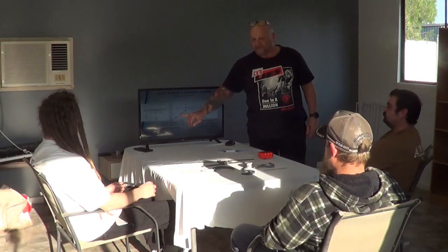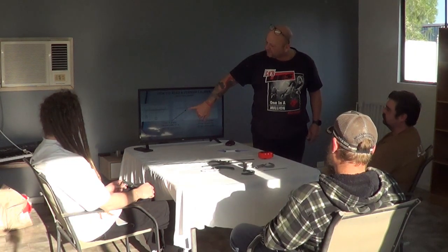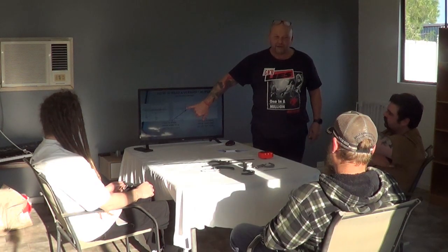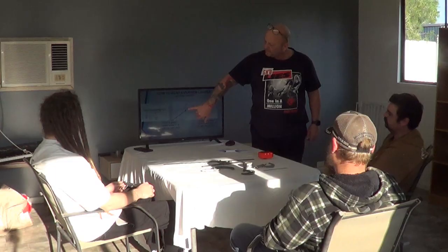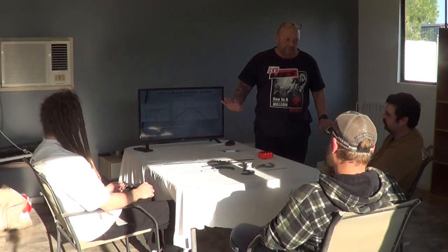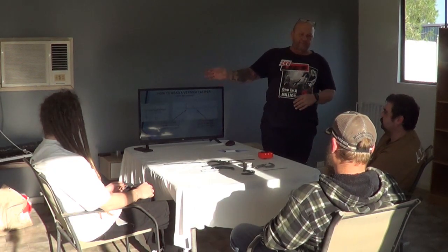Alright, so on your vernier scale, there's a 0. Your first measurement is millimeters. Wherever the 0 has passed is the number of millimeters. On this example, the 0 has gone past the 11th millimeter. It has not gone past the 12th millimeter yet. So you know you're on 11 millimeters, and it's 11 point something.